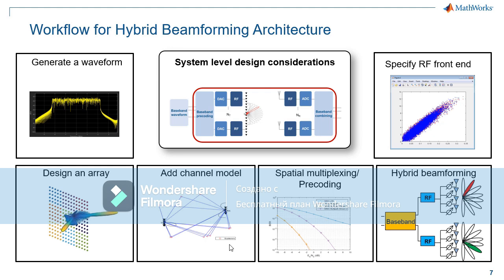And based on that, if you want to use spatial multiplexing and send multiple streams on different antenna ports, you have to compute the pre-coding matrices, which are the digital beamforming requirement. The digital pre-coding matrices multiply weights in the digital beamforming architecture in order to steer your signal digitally to the direction that you want.